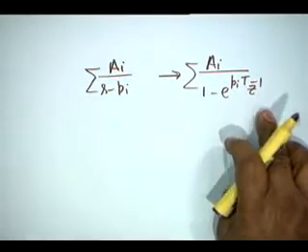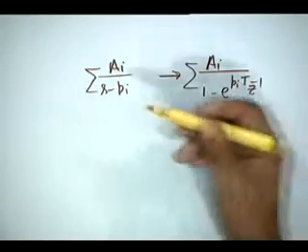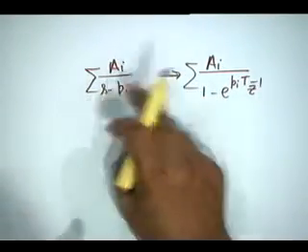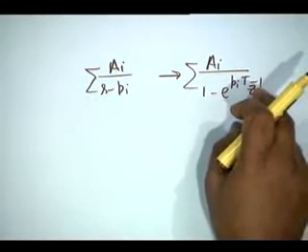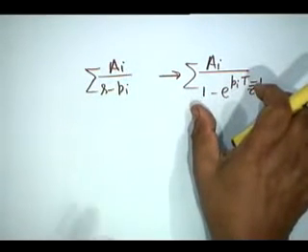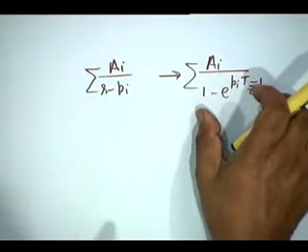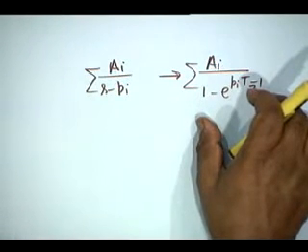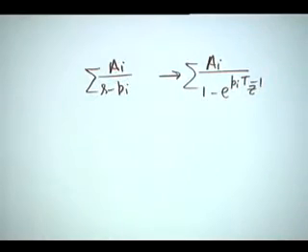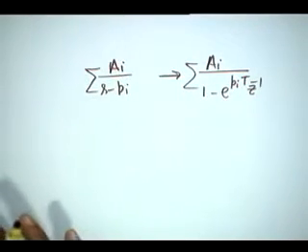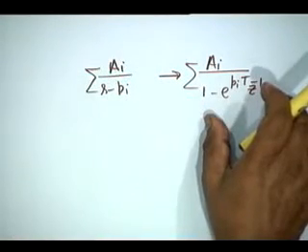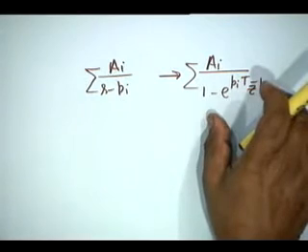The zeros of the transfer function from the analog plane are not transformed according to this relation. Whatever zeros come, we will have to accept, and this arises because H A of s is not band limited. This is how it is reflected. Since we have no control over the zeros, the transfer function that we get shall not be exactly what we wanted.